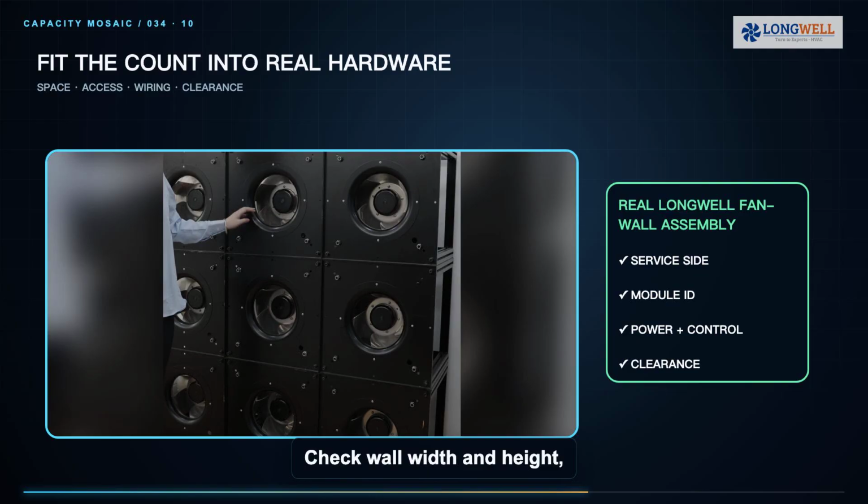Now fit the arithmetic into real geometry. Check wall width and height, module spacing, access side, lifting path, cable routing, guards, isolation device depth, and downstream clearance. Poor inlet or outlet geometry can change array performance. AMCA's fan array method combines individual contained fan airflow at constant static pressure, but the real module, partitions, controllers, and appurtenances still affect the assembly.